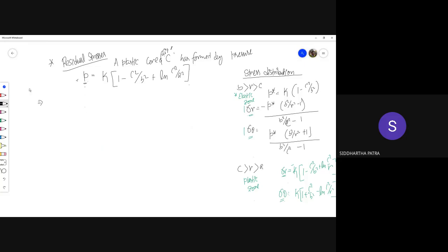So you increase the pressure from 0 to P, okay, and let's say somewhere over here you encountered P prime where the plasticity was initiated in the cross section, and now you are somewhere over here at P, and then you are trying to unload over time, and by the time you unload, the pressure becomes zero, but the stresses may not be zero. Actually, the stresses won't be, and that's why you have the residual stresses.